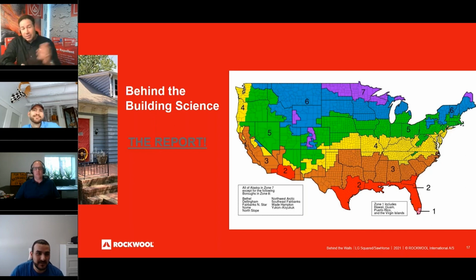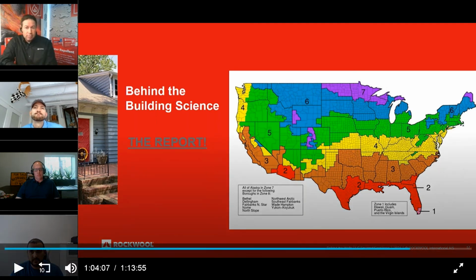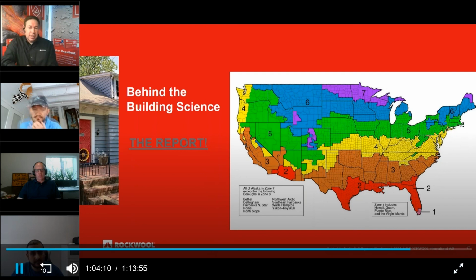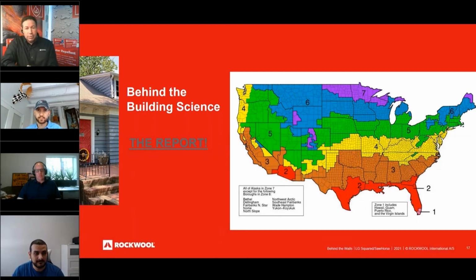And the big thing, I wanted to bring back the black part of the mold growth. That's something, if you were on the last webinar, we actually showed a failing system up in Minnesota, and it was basically a trap system with vapor barriers on both sides of the wall system. So Ollie put that one together, but that's something that does not come off pretty. The insulation would be a lot worse if it was a mold supporting product in that wall. So thank you, Ollie.